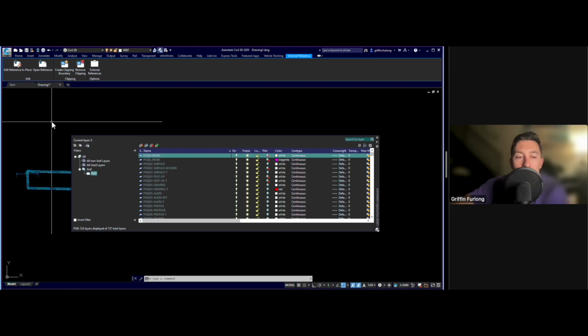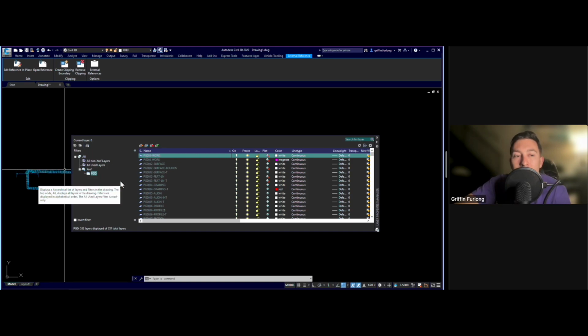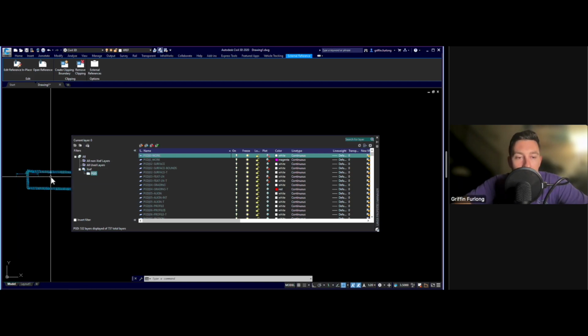That's not what I was trying to do. What I was trying to do was just change the color and styles within this drawing, because if you change the source drawing information, you're changing it in every other drawing that it could be referenced in. That's a really important lesson that I can't emphasize enough. So let's actually check out what I'm talking about here.